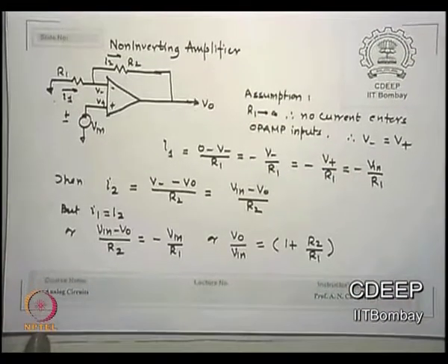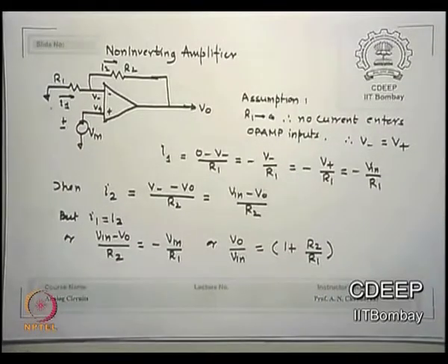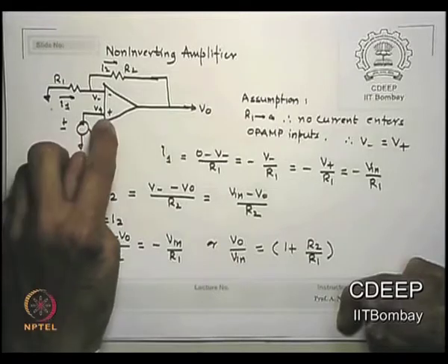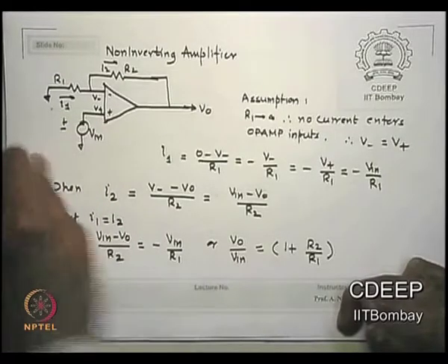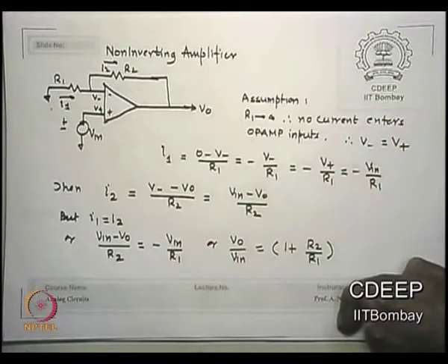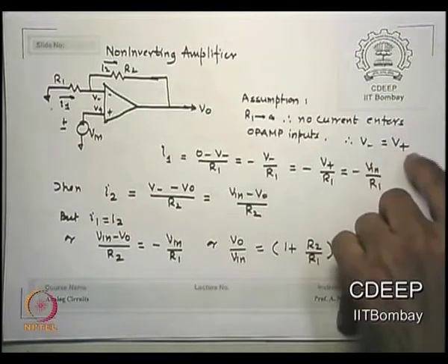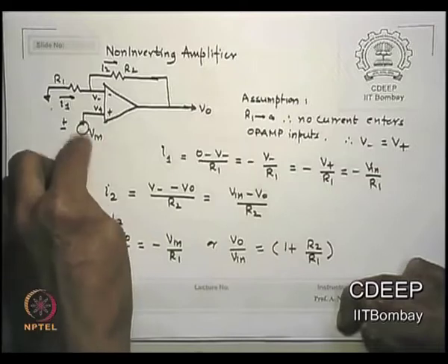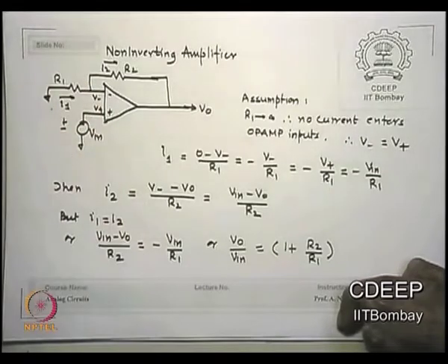Before we quit, let's quickly see by same logic a inverting amplifier. पहले देखा, अभी what is inverting means? Minus R2 by R1 is a phase shift of 180 degrees, so we say inverting. If I apply a input at the V plus, okay, and still we assume Ri is infinity and AOL is high, V minus is still V plus, so ये V in है तो ये भी V in ही है.